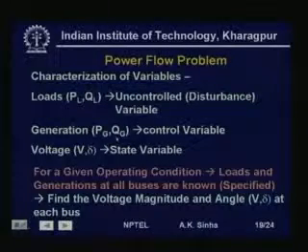So, he adjusts this generation at various bus bars so that he gets an optimal performance, and therefore, these generation variables PG, QG are our control variables, whereas the voltage magnitude and angle at all the bus bars, which basically relates these control variables as well as disturbance variables in the system, are the state variables of the system.